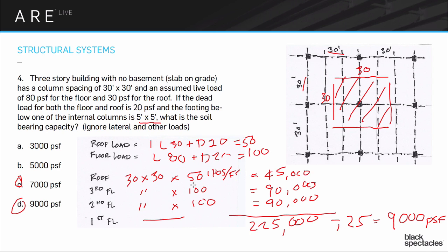So you'll find the sort of soil capacity loads, they'll range between, probably the smallest load you'll ever find on the exam would be something like maybe 1,000 or 1,500 PSF. That would be pretty not great soil and would only be really usable either in like the mat or raft like we just talked about, or in something of a fairly small scale type structure. Anything that was a bigger scale structure almost assuredly would be at least 2,000 PSF and probably 3 or even 4 or 5,000 PSF for what you'd be looking for in that soil.